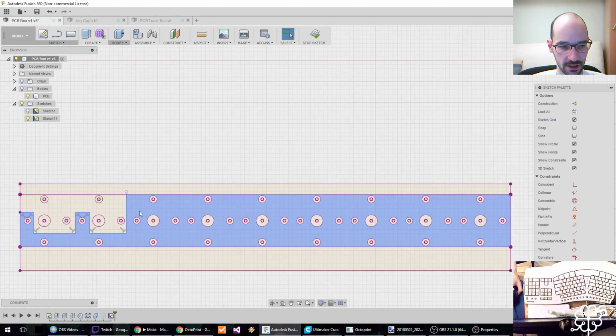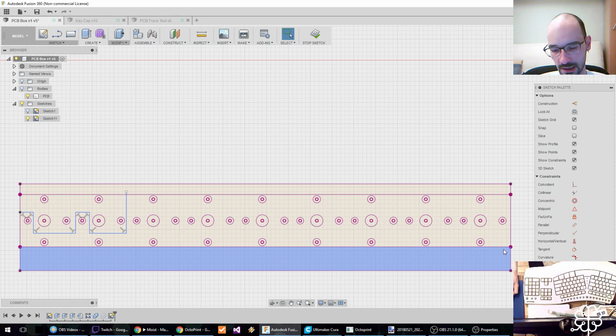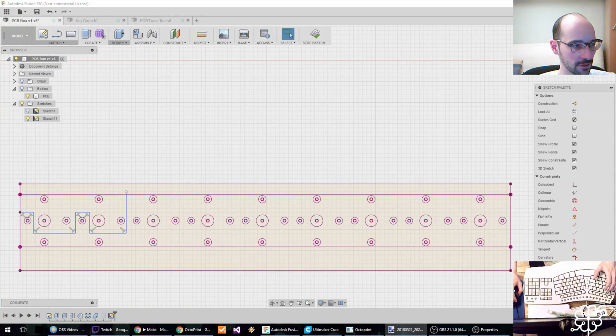Now, I could also have it so that, like I said earlier, just route these few signals together, and then have a wire coming out from here all the way to the end, and another wire coming out from here all the way to the end, and so on. That'd be a little less clean. Another thing I could do is to route the signals all the way to the end, but then change the order of the wires, such that, for example, if you're looking here, this red wire here, I could actually just route it on the bottom. I wouldn't really care. But then there'd be like this opportunity for screw-ups, basically. We'd have to know to connect this wire up here in the third position on the keyboard's motherboard. So again, if I can avoid it, I'd prefer to avoid that.